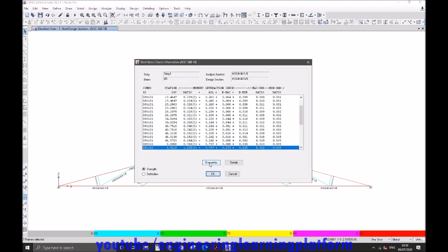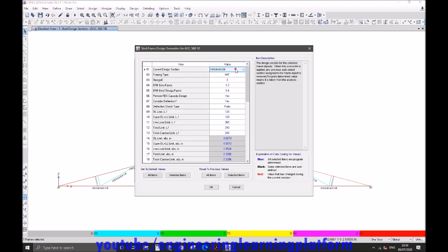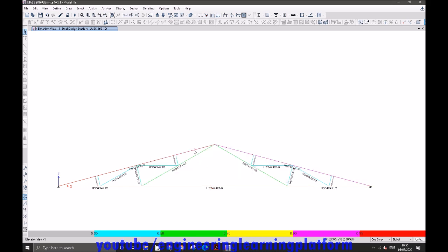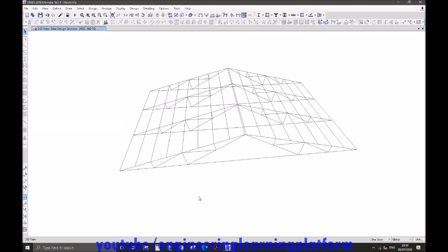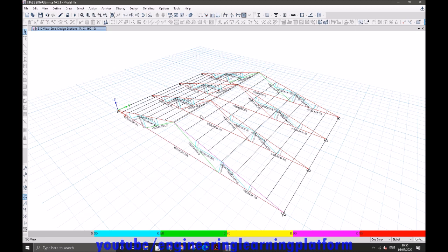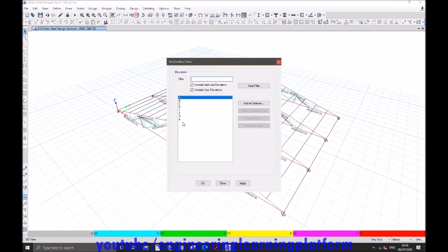But for the internal truss, I'm sure the internal truss would be failing if I assign the same size to it, as the tributary width of the internal truss is twice that of the external truss for gravity loads. So in the next run I'm doing that. I'll unlock the model.